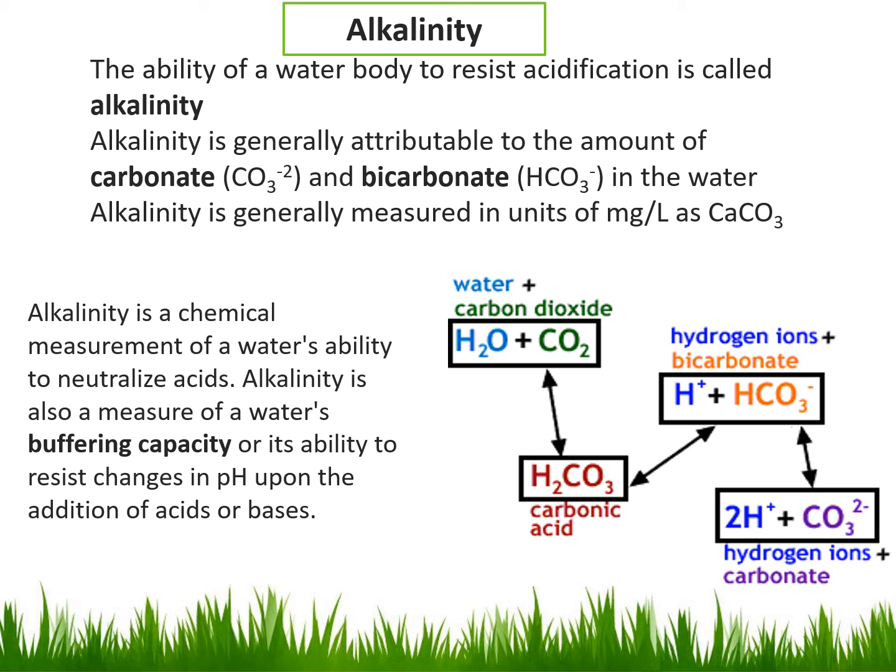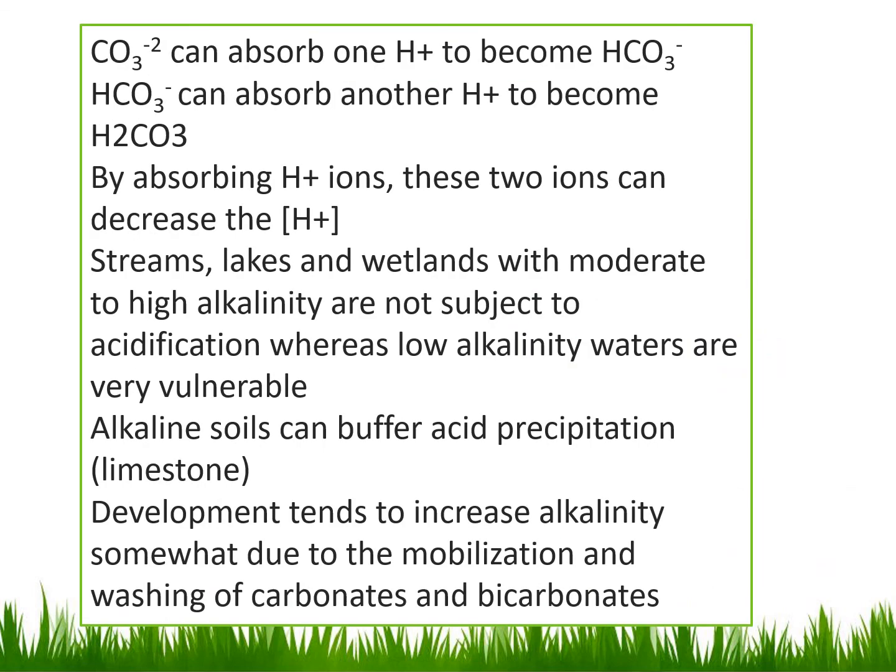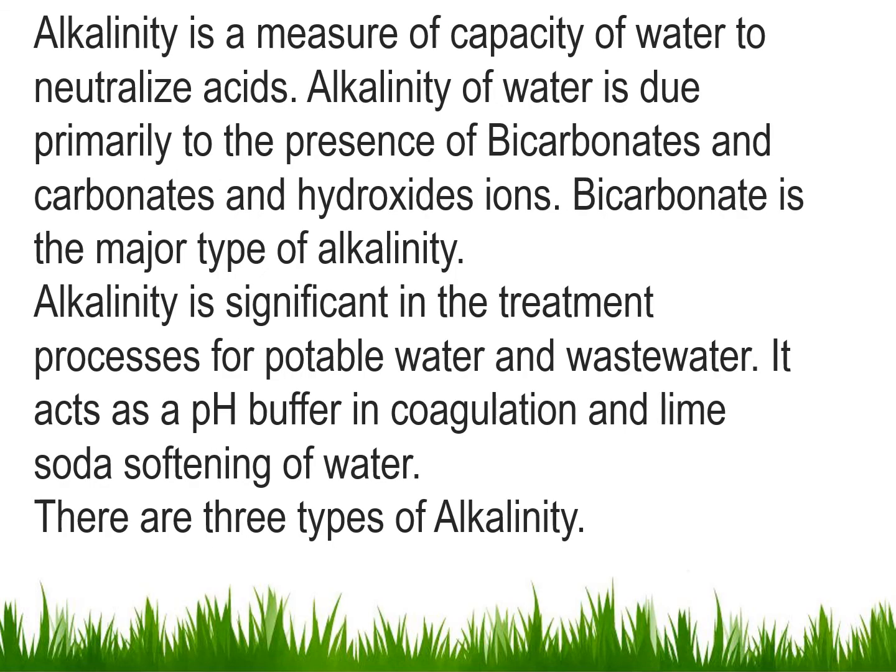This is the first process in which acidification is conducted. Carbonic acid is formed like this. It further dissociates into H plus and HCO3 minus, and then furthermore it is separated into the carbonate ion. This carbonate is insoluble, as we studied previously. Now once it is insoluble, that means it has the possibility to be removed. That's it. Please go through it, and it's kind of repetition.